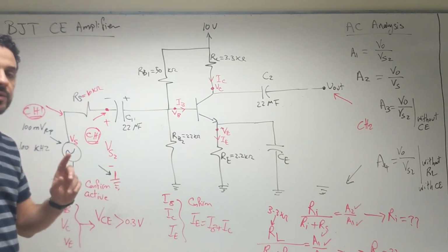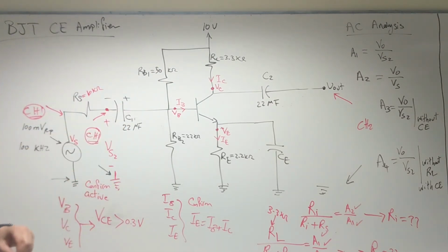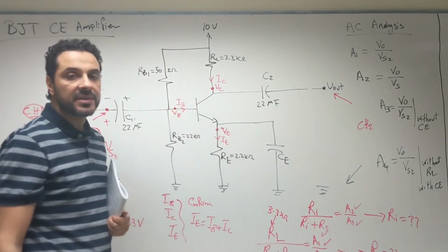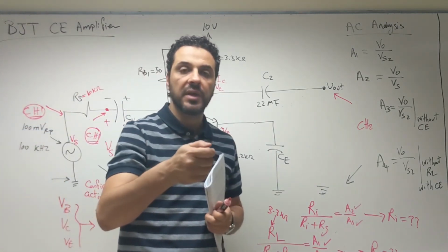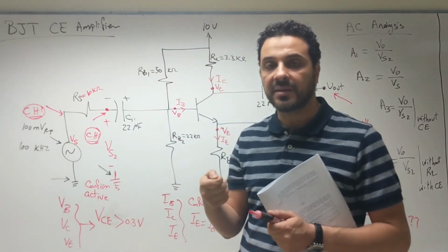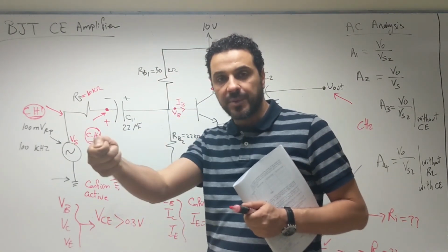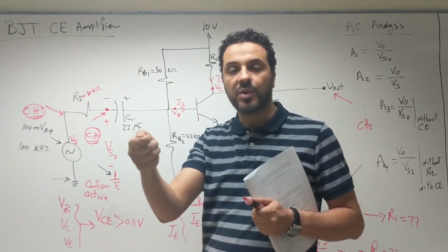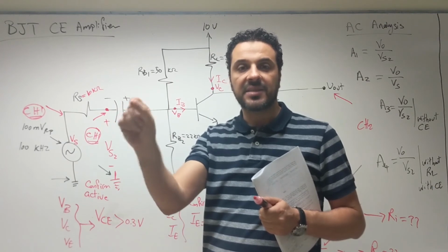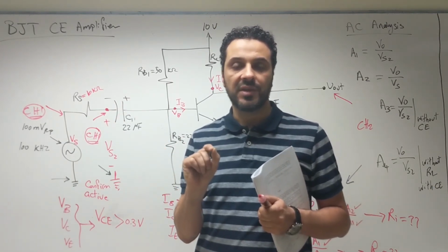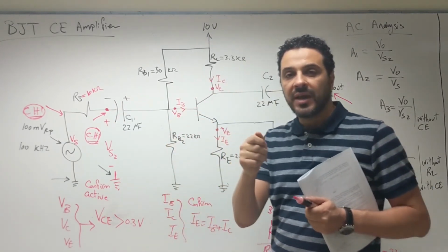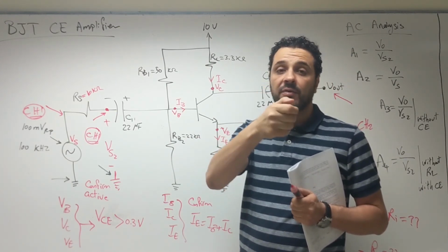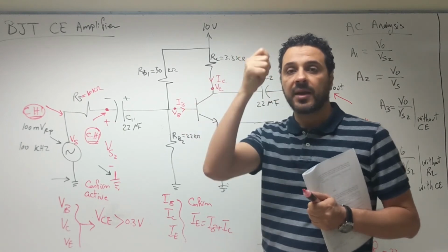I forgot to say something. When you measure the currents in the beginning in the DC circuit, you have to connect the multimeter in series. First, you have to remove the red cable of the multimeter from the voltage terminal and put it in the current terminal, okay? Because the current terminal in the multimeter is different from the terminal for measuring voltage. So the first step that you should do is remove the red cable from the voltage terminal and put it in the current terminal.